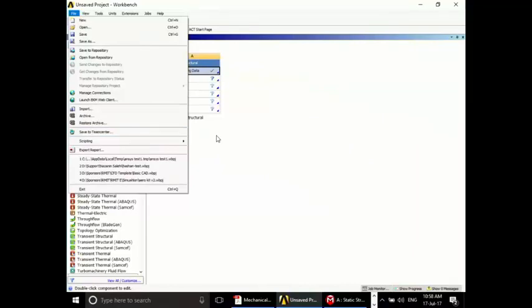Just while you're solving, because it has to write temporary files to the same location as the project, if that's on a network drive, and if it does actually let you solve, it will be very, very slow. You want all of the disk activity to be between the local hard drive and the CPU on your machine, because otherwise it uses the network bandwidth rather than the local disk I/O inside your machine, and there's a factor of a few hundred difference in those two.